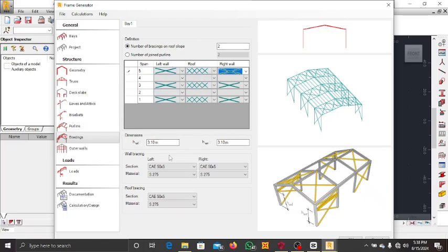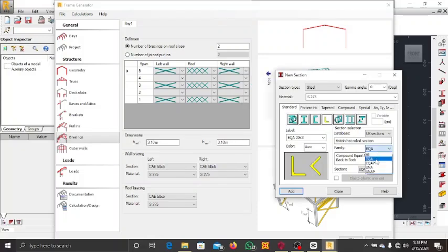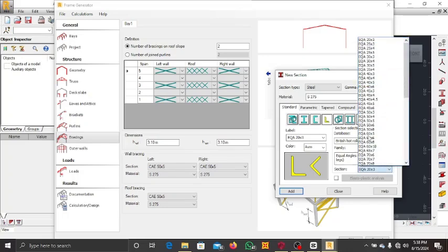So for your wall bracing, what members do you want to use? Let's say we are going to be using angle irons for the bracings. So we come here, equal angle, we check it's not here, come to more. Okay, these angles, family EQA, equal angles, x and y axis parallel to legs. So for equal angles, we are going to be using 70 by 7 for our bracing.